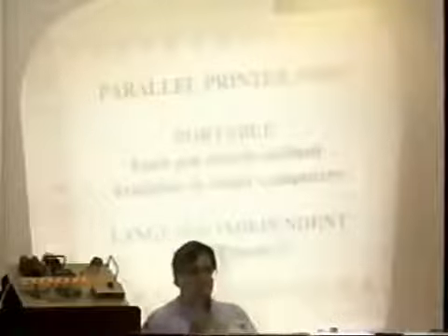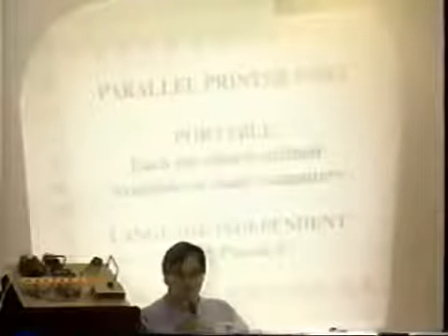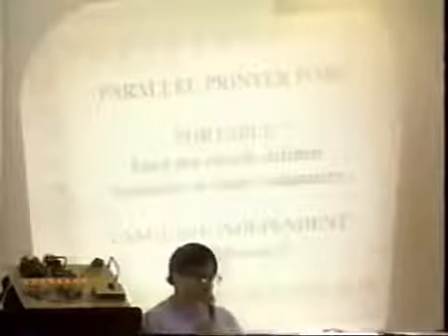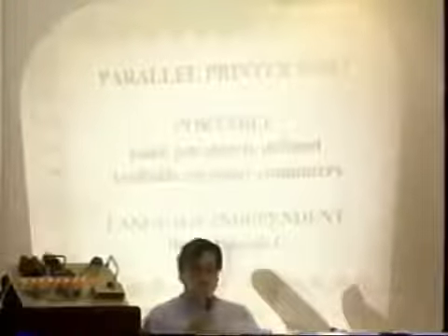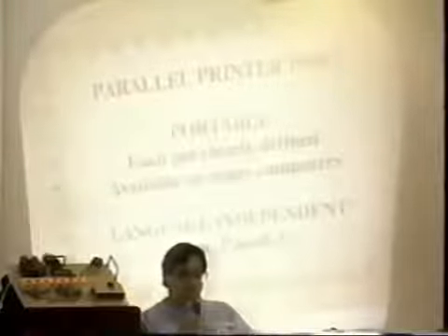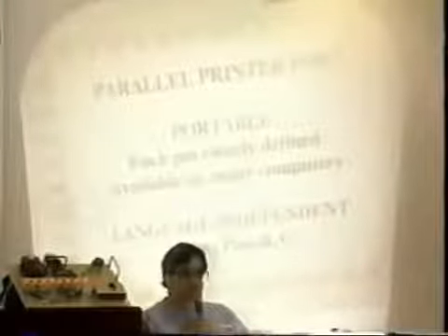With a parallel port, every single pin was defined by the Centronics company when they made their first parallel printers. And everybody uses the same pins, and they all mean the same thing, and they all do the same thing. Nothing is different on any computer. They're all the same. We can use this then, and by the way, when you're talking to a printer, every language has commands to talk to a printer. In BASIC, you can say lprint. In Pascal, you can say write or writeln. And in C, it takes about a page of code, but it still works. You write your own, right?